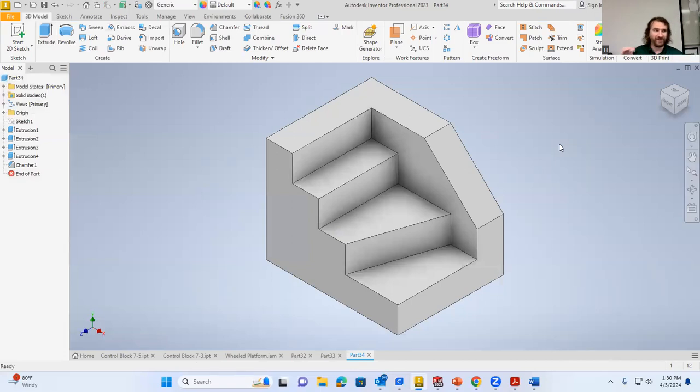Very short, very simple. Again, with a stair step object like this, look at the top view. Make those profile shapes and then just extrude each of them what they need to be extruded. And then add any additional features after those extrusions are done, in this case, a chamfer, right? So look at anything that has these kind of stair step effects, and you'll be doing fine. You'll be doing really well. So this was lesson 15. Very, very easy, very simple to do.